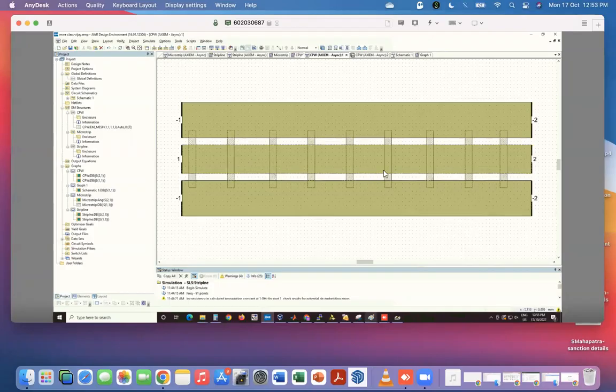See, a CPW mode wave will encounter 50 ohms at either end. So once it hits that, it cannot reflect. But the slot line mode is going to encounter a short circuit because the two ground planes at the end are connected to each other. So that looks like a length of transmission line with two shorts on either side. Then you can get things bouncing back and forth, and you will also have energy converting between the slot line and CPW and back. So you will get some weird resonance because of that. That's the reason you have to suppress it.